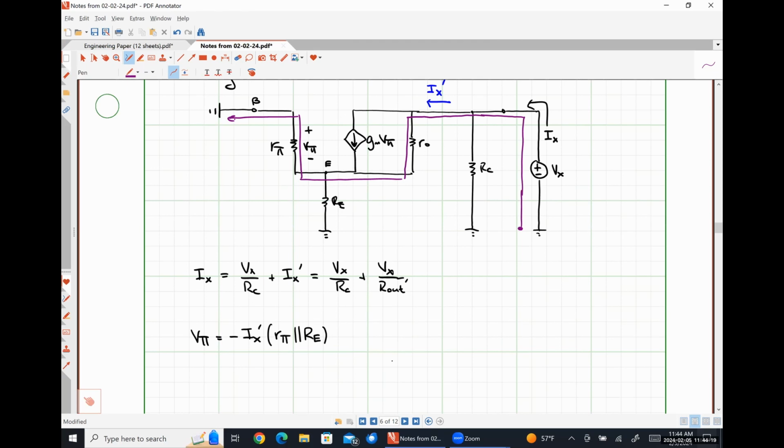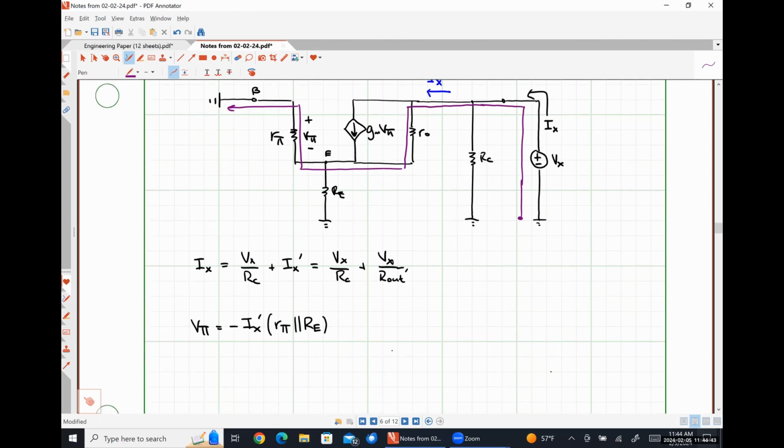So this is a valid path by which to apply Kirchhoff's voltage law because I'm starting and ending at the same node. So what I'll have is Vx is equal to the voltage drop across this resistor plus the voltage drop across that resistor. Nothing remotely crazy or fancy here, just Circuits 1 level stuff applied to something a little gross looking, right?